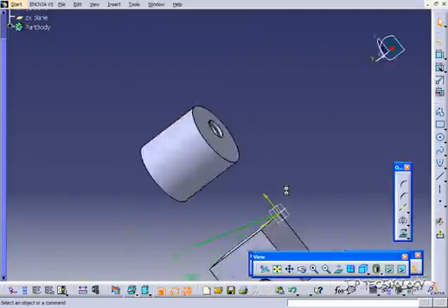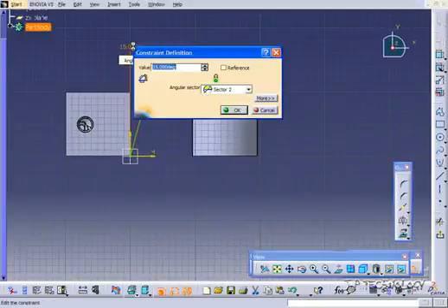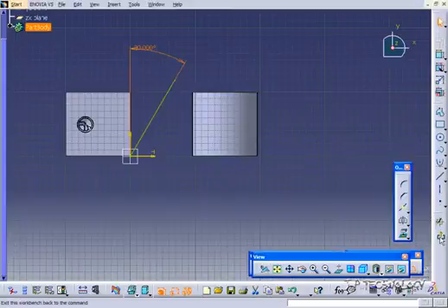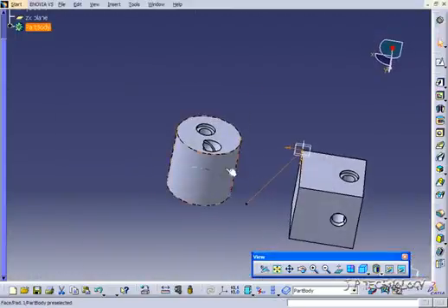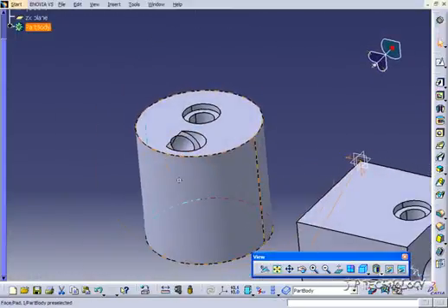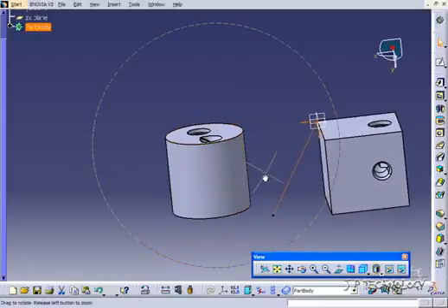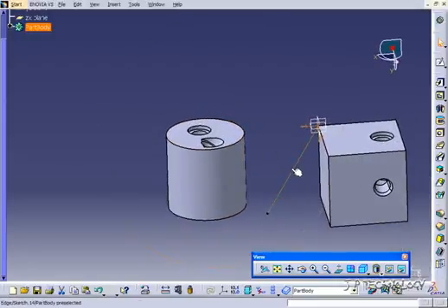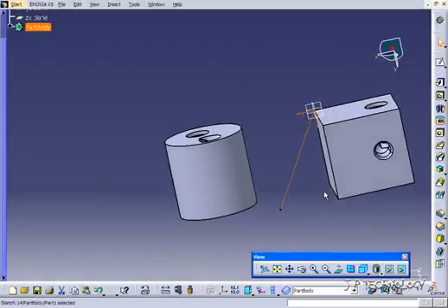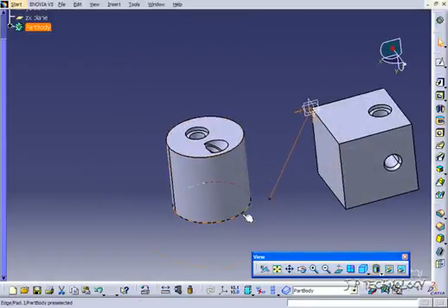Now if we double click on this line and say we change this to 30 degrees, then everything's going to automatically change. So let's go and update it, and now it's on a 30-degree angle. So when you're making the hole, you're able to either align it with a sketch line or an edge. So say that there was actually a solid here that was along that line, you're able to select that line too, and it's going to follow that line.